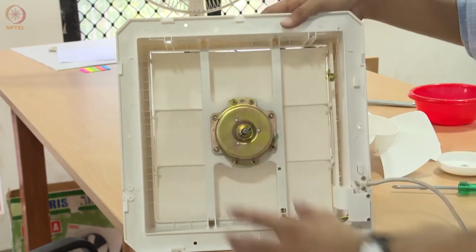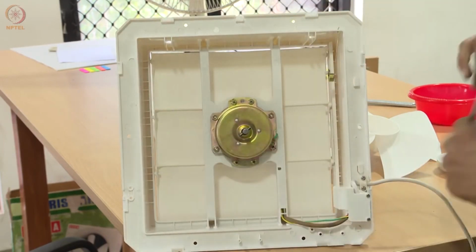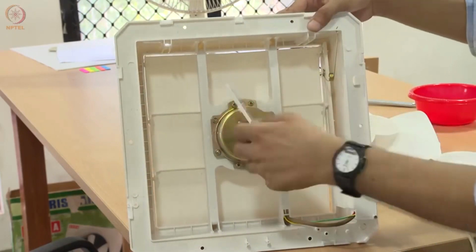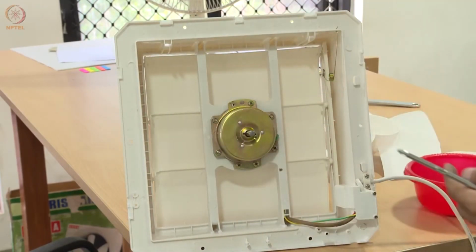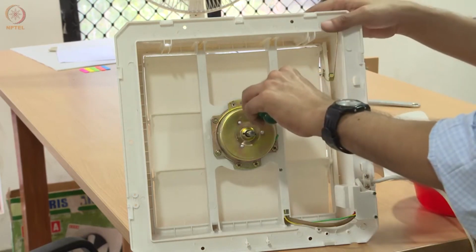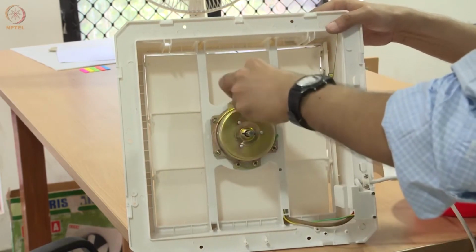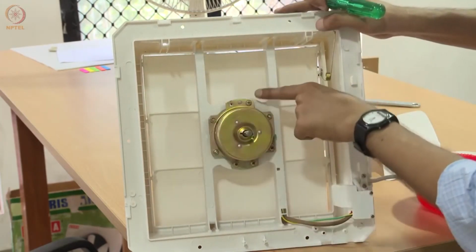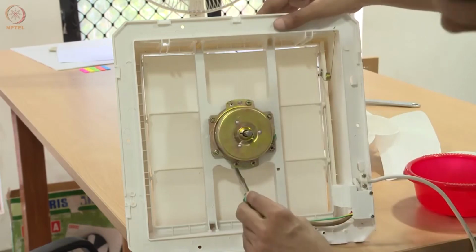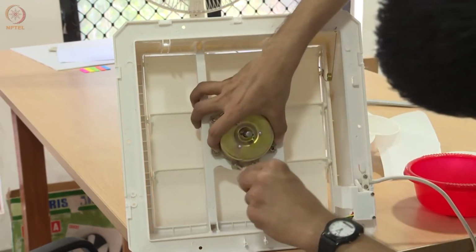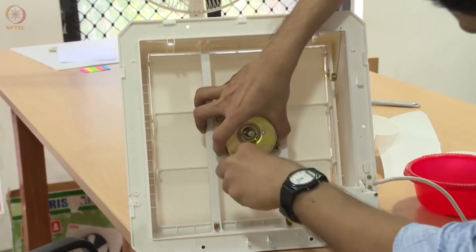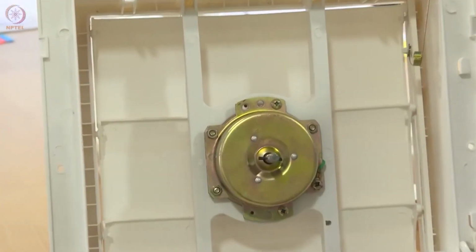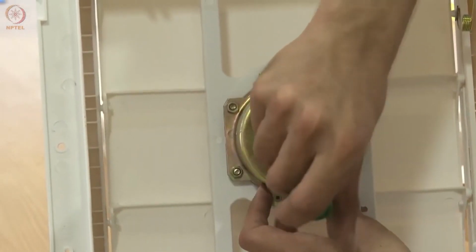Okay, now let us look at the motor itself. Let me dismantle the motor just to show you. Keep track of the screws here. It is always good practice to leave the topmost screw because it is hanging. Remove the bottom screws, so that the motor is hanging by one screw, and then we can finally support the motor.